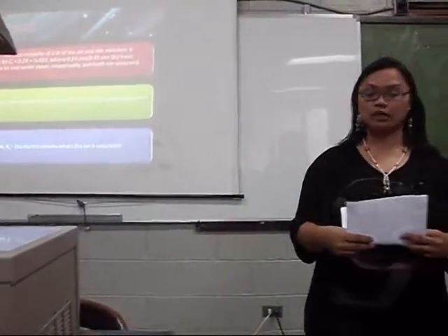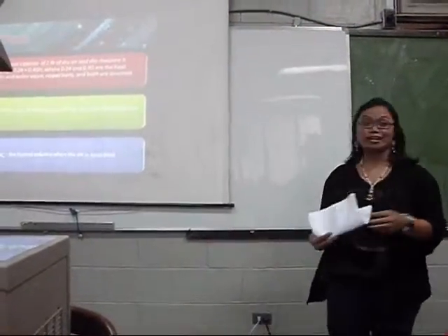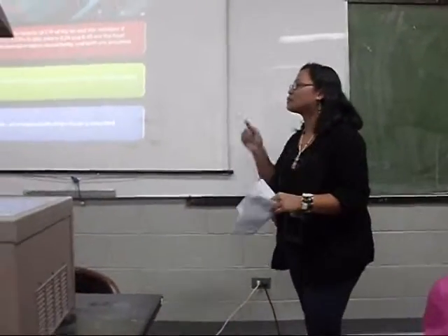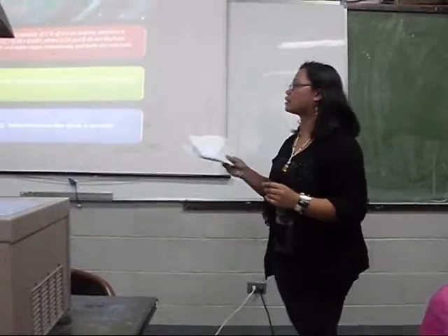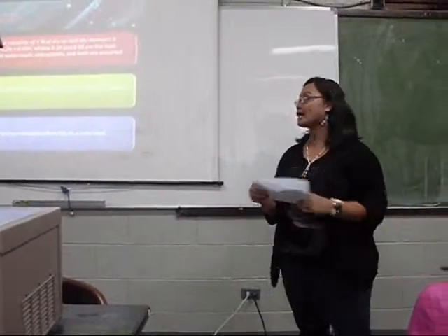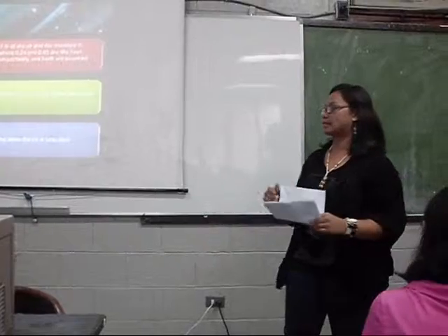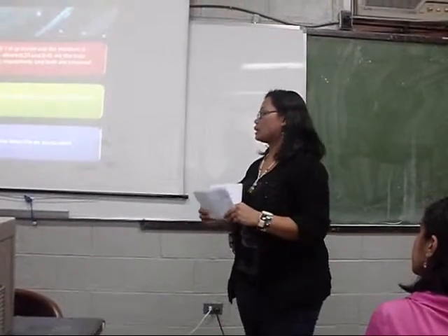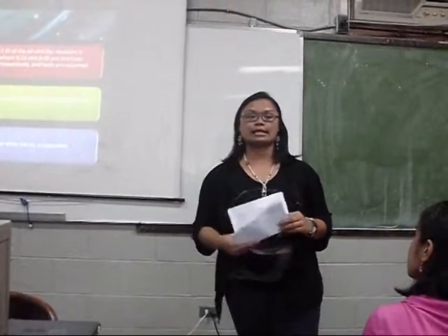Next, we have humid volume. So there are a lot of terms, so don't be too confused. Alright? So humid volume is the volume in cubic feet of 1 pound of dry air and the water vapor it contains. And saturated volume, V sub S, is the humid volume when the air is saturated.